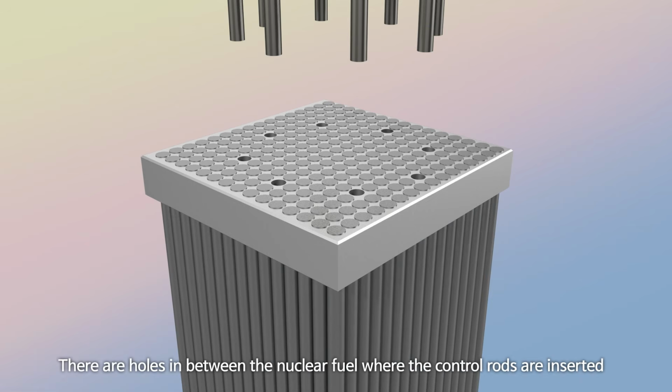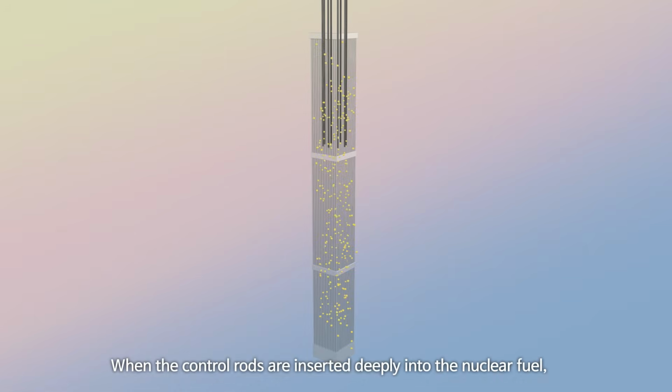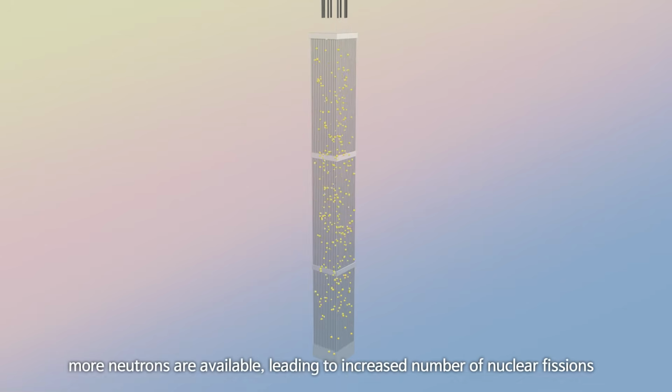There are holes in between the nuclear fuel where the control rods are inserted. When the control rods are inserted deeply into the nuclear fuel, they absorb more neutrons, reducing nuclear fission. As the control rods are raised, more neutrons are available, leading to an increased number of nuclear fissions.